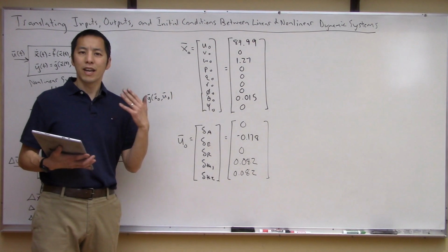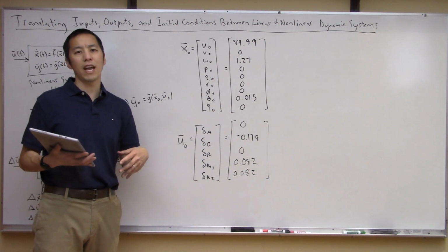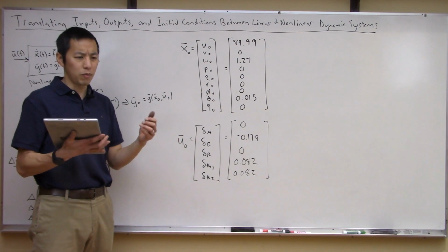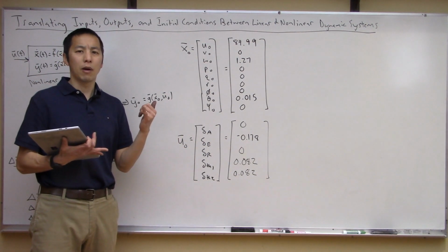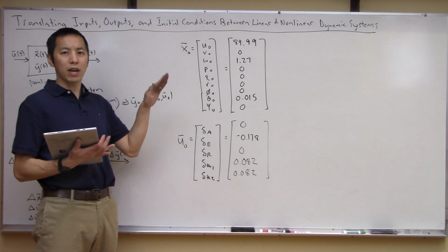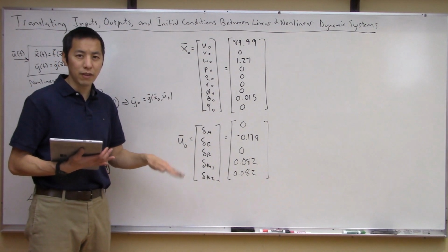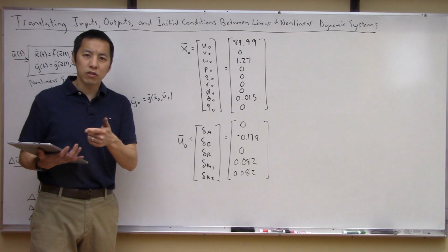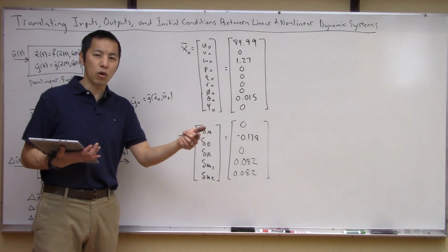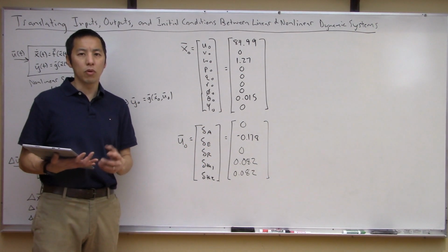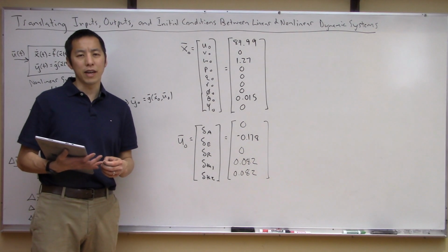So now why don't we jump over to Simulink and let's just simulate a bunch of these conditions of, you know, non-zero initial conditions? How about some elevator input doublets where we kind of pull back on the elevator and then push down on the elevator and let it go? And again, the goal is to do it both in the linear system and then apply that exact same equivalent condition in the nonlinear system and see how they stack up. So let's jump over to Simulink and do that now.